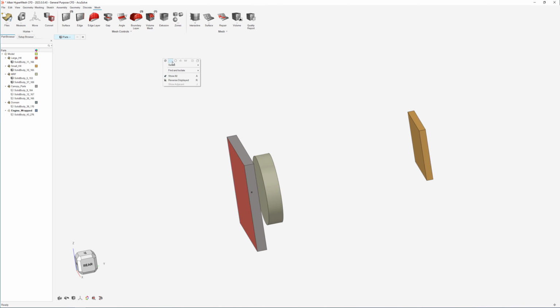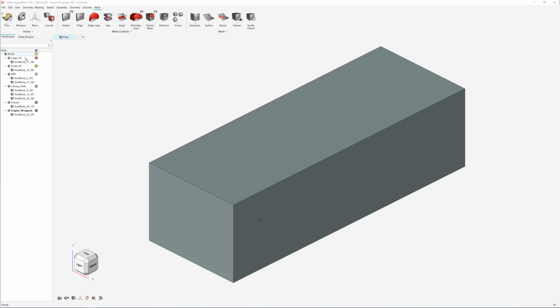At this point of the pre-processing phase, we will delete the solid parts, which will not be included in the simulation. The reason why we kept them until now was the easier manipulation of their surfaces for defining the mesh controls along with the boundary conditions. If we deleted them earlier, we had to manually hide all domain surfaces to reveal them each time, making the process slower and less efficient.